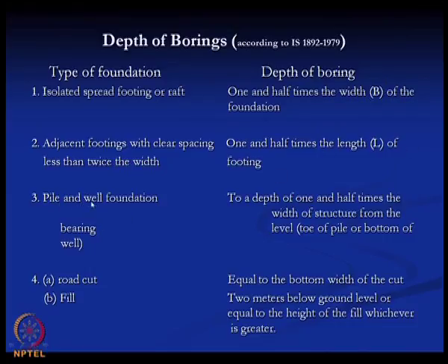Then if it is a pile or well foundation, to a depth of 1.5 times the width of the structure from the bearing level, that is, the toe of the pile or the bottom of the well.